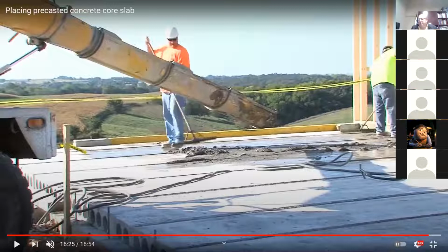Now the problem is, just imagine you have a cable inside the sleeve with some grease, and you have 2 anchors, one from each side. And then you come in the middle and cut the cable. What's going to happen to one of these blocks, like the anchorage at the end? What do you expect? It's going to fly out, and it can kill anyone easily. Maybe 2 people. If it hits a couple of people, it's just going to kill them. This is a problem. It depends on the type of slab that you have. And also, once you cut the cable, you lose the pre-stressing, and you cannot put it back.